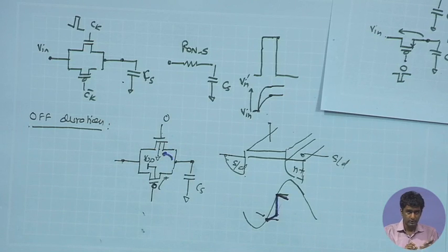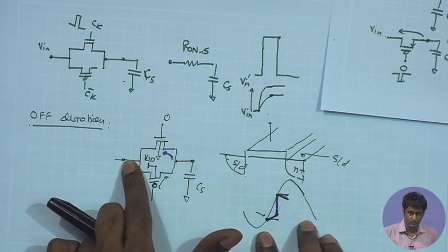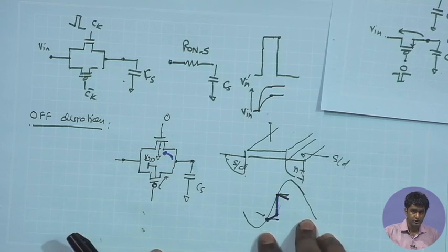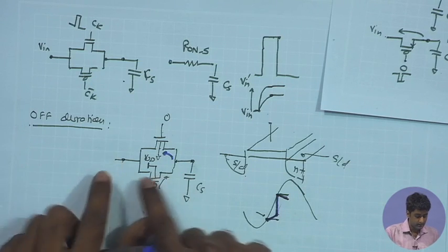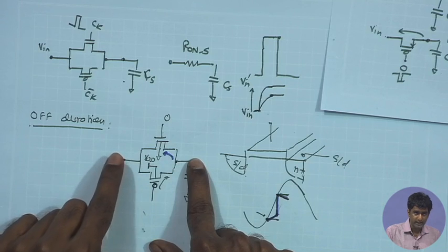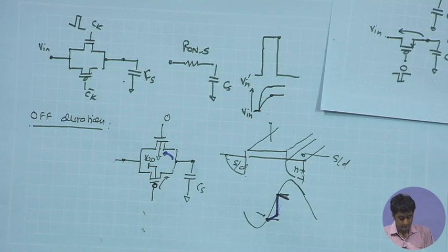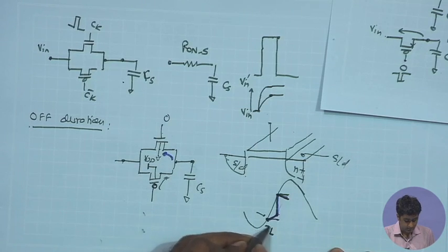So, if you are looking at scaled technology nodes, say 45 nanometer or lower, there the subthreshold conduction can be dominant. There also, of course, the signal over here will change as compared to the sampled value, but at least it will be trying to follow the direction of the signal at this point. So, in this case, I say that this is for the junction leakage being dominant.